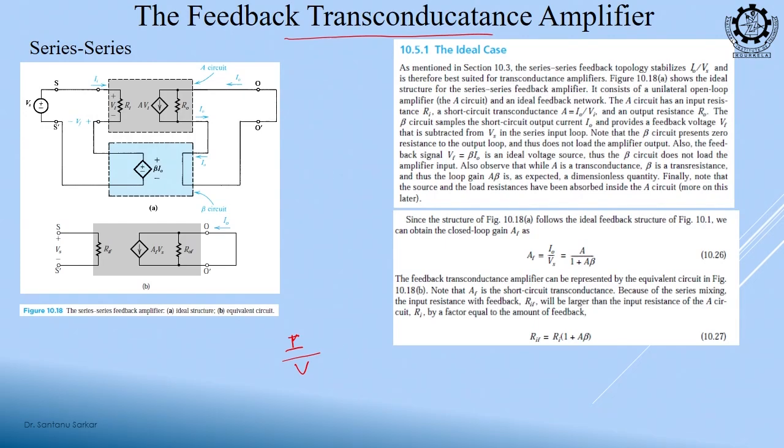And can you see the connections? What are the connections? If you want to flow the same current, the connection should be in series. So, this is in series, so that same current flows, right. If it is in series, same loop current will flow, and if you want to add or subtract voltage, that should be also in series.